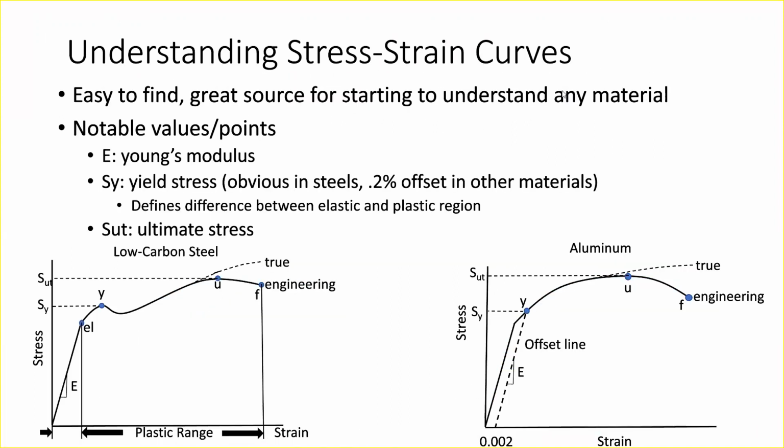Oh, there we go. Okay, so yeah, we use these plots called stress-strain curves to describe these relationships. If you look at this plot right here, on the bottom axis you have the strain, or the relative displacement, and on the y-axis you have the stress, or the normalized loading. As we were saying before, there's a fundamental relationship between the amount of load that the part undergoes and the amount of displacement it undergoes.